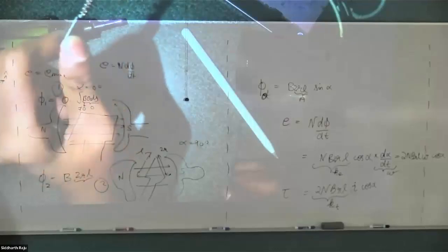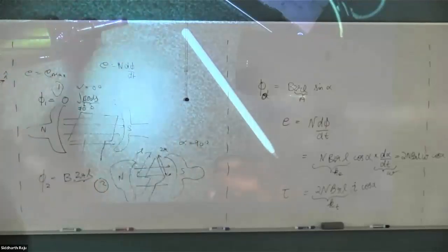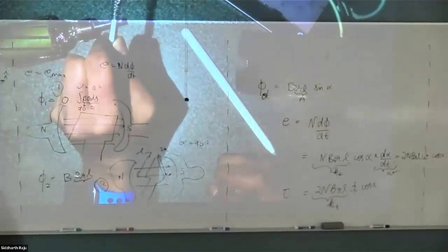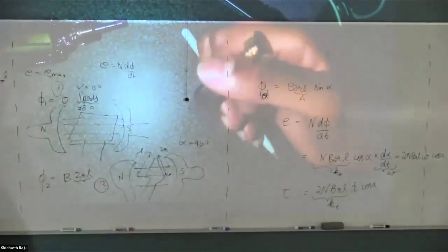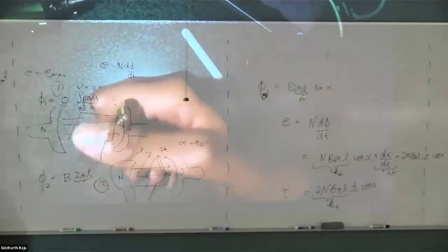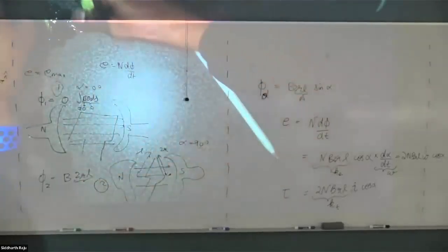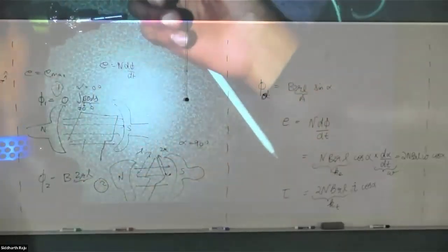They would have to replace this every 3 to 6 months. Even in our labs, we would have to replace it sometimes. When you do some experiments, you'll see that as you rotate the rotor by hand, the resistance that you previously measured is not the same resistance, right? Because as it rotates, sometimes it makes good contact, sometimes it doesn't make good contact.